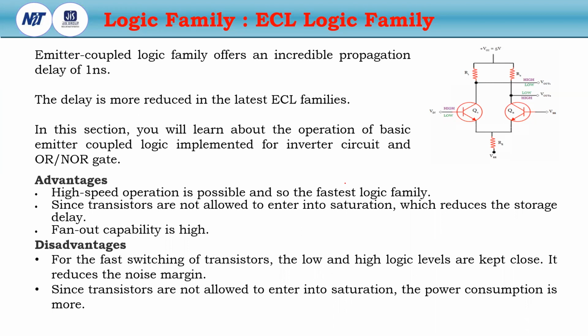Since it is not allowed to enter saturation, the power consumption is very high. So the disadvantages are high power consumption and low noise margin, due to the very small voltage levels.